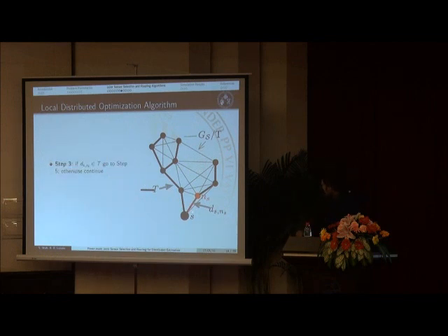We have to check if this link is in the tree, that is the non-spanning tree, due to the subset of K sensors. We check whether this link is present in this tree or not, because we are going to swap an edge between the tree and a link that is not in the tree, so that we can improve the power. Here it is in the tree, so we don't have to swap. In the next step, we assign this sensor as the sink, and then find again the nearest sensor to it. For example, this is the nearest sensor to this S. And in this case, this link is not present in T.